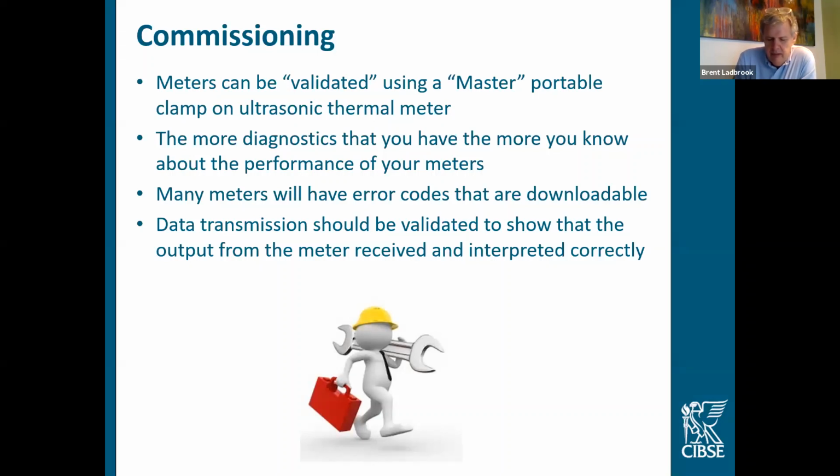You have a meter or a flow sensor that is calibrated, and the volume going through that is traceable back to the 1 kilogram unit in France, albeit now virtual. The temperature probes are paired and matched and calibrated, supplied with a certificate, calibrated to the best of European standards that are readily available. The calculator is calibrated. You install it correctly. If there's no error codes in the meter, I think we're pretty safe in saying that that is working properly.